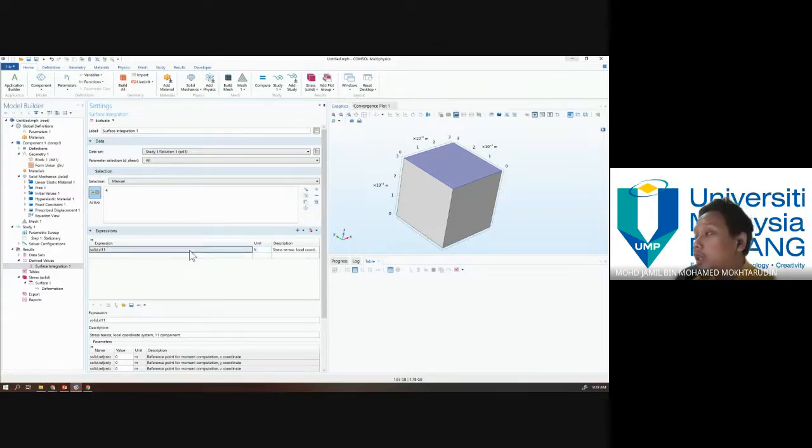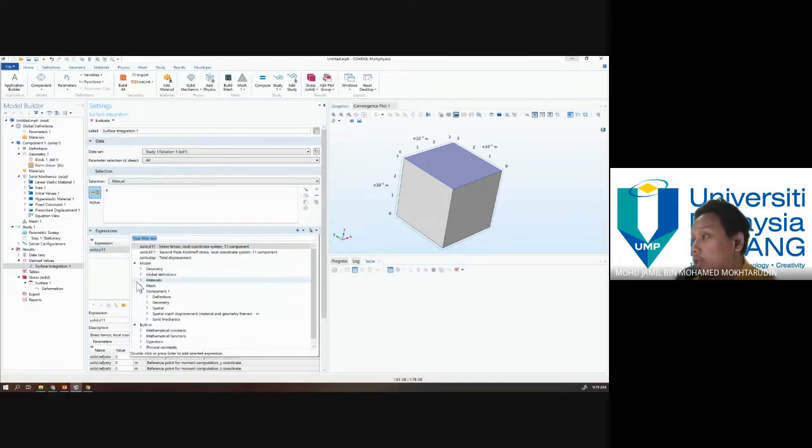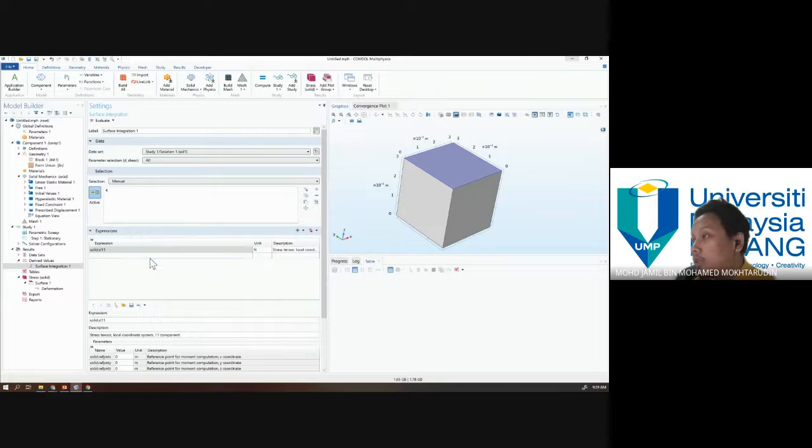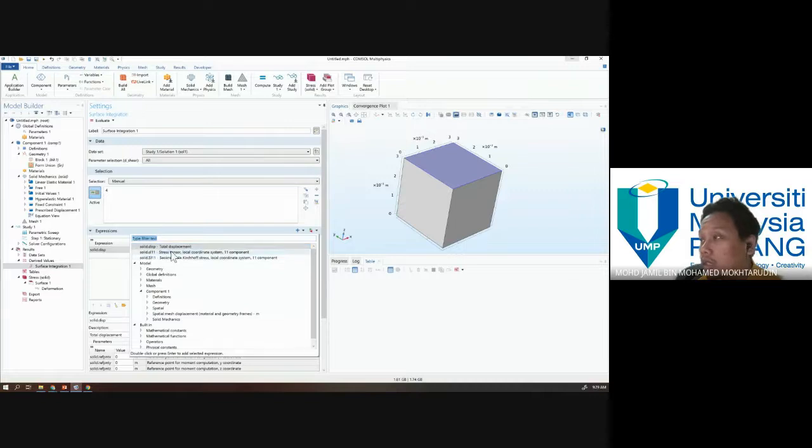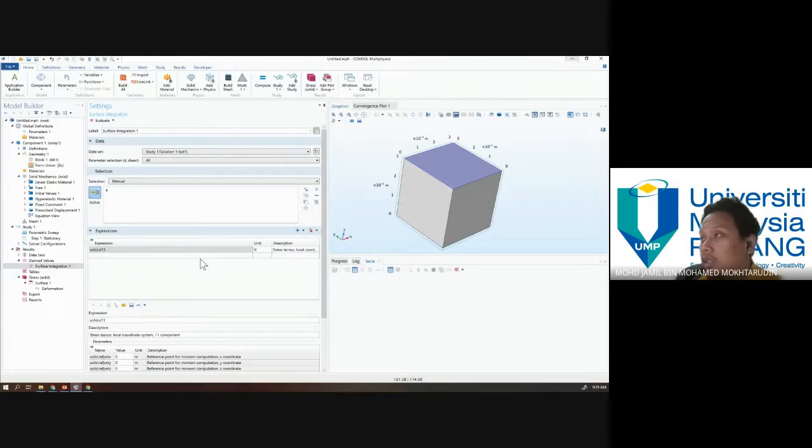So here, if let's say when you choose a different expression, for example, if you choose displacement, so here the unit becomes meter cube. So it doesn't give you Newton, meaning that you choose the wrong expression. Okay, so if you choose stress and integrate stress on an area, you will get a force. Okay, so here the unit indicates whether you get a force or not.